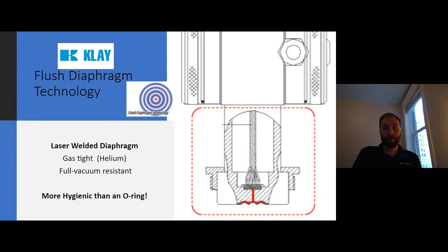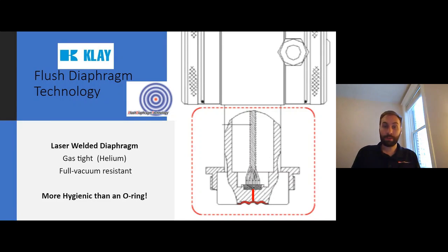One of the reasons that something doesn't work 2 months after the fact is because possibly, even indoors, you've got changes in the ambient pressure and the ambient temperature. You've got winter and you've got summer. And those changes in temperature can affect some things on some transmitters. Here is our flush diaphragm technology. One thing that it can affect is fill fluid.